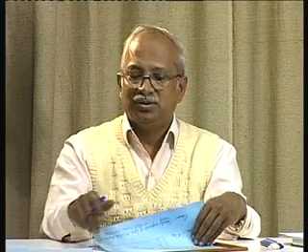Is that clear? Okay. Now, what are the other components of resistance that we are interested in when the ship goes to sea? We have talked about correlation allowance. Did I talk about it before? I think I did. That is, when you do a model experiment, the model is very smooth, and when you come to a ship, a new freshly painted ship, the smoothness of that surface is slightly different from the model. So, to take into account the roughness of the surface, we put a small allowance called CA or correlation allowance.